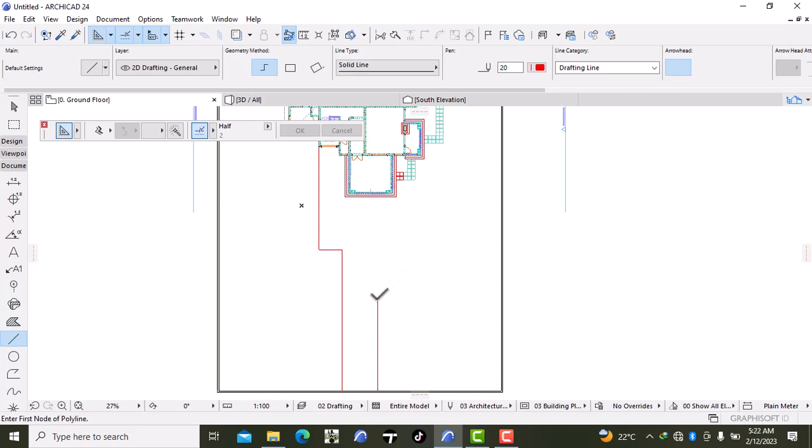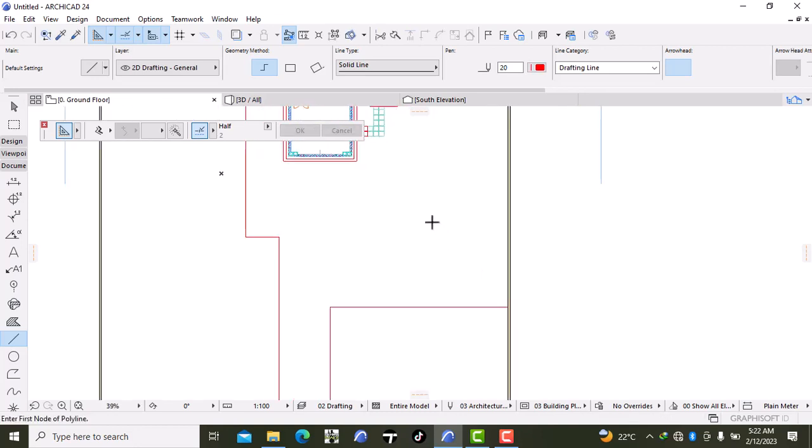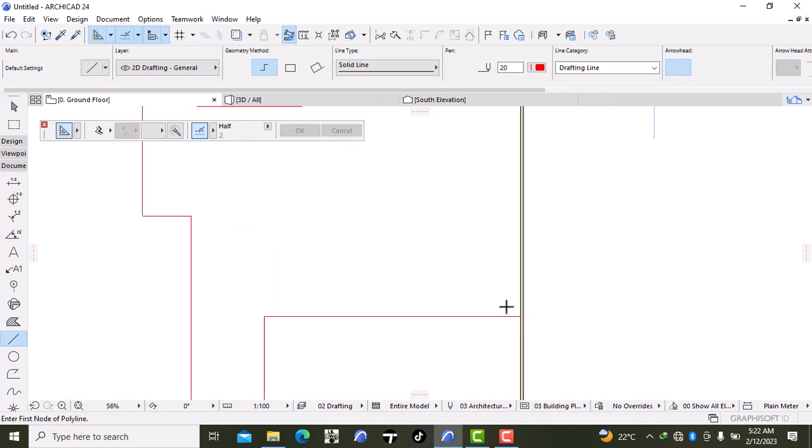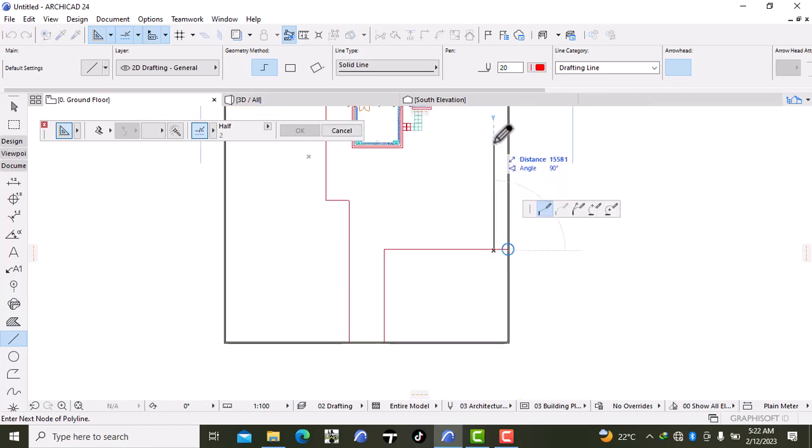Just work with this line tool. Just drag it from this side to somewhere like that. And basically, can do the same over here. Do a line from this point, at a distance of 2000, press enter. Can still have something like this.